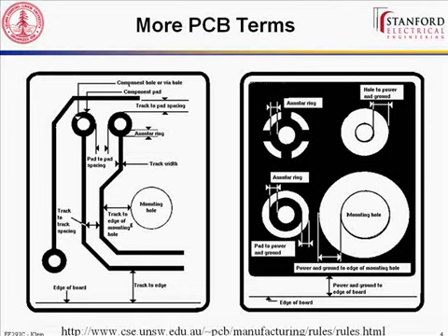So any other questions? So the annular ring is a minimum width of the ring required. If it's any thinner than that, they can't guarantee your holes will plate, and they yell at you. But you can have the annular ring as large as you want.